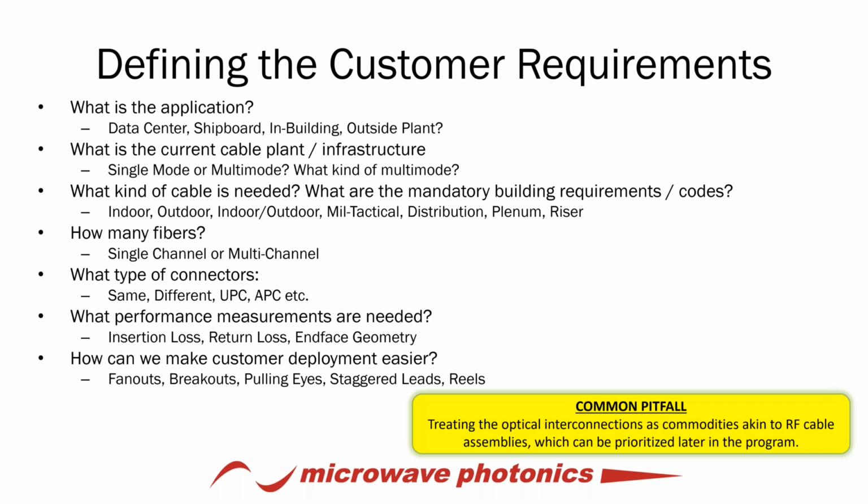So the common pitfall here again is treating the optical interconnects as commodities akin to RF cable assemblies, which are prioritized later in the program. I really urge anyone considering this to put that up front. Treat the fiber optic cable as much of a critical component in a transport system as the physical transmitters and receivers themselves. You can't look at the fiber cable like a traditional coax connector. You need to look at it as a waveguide.